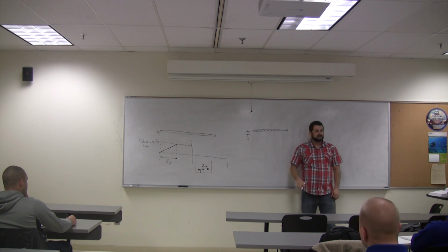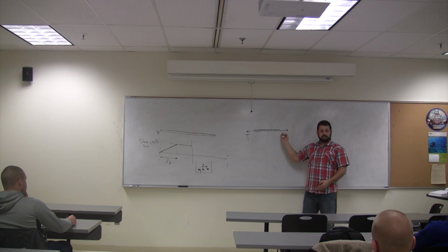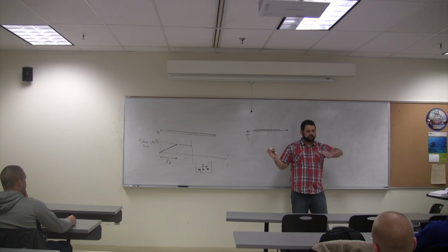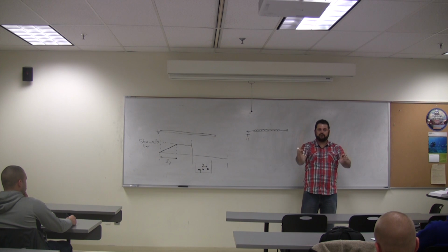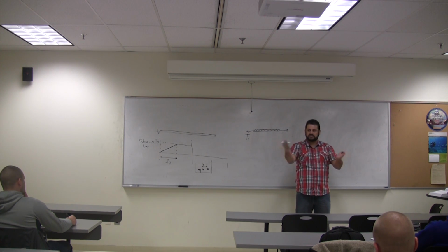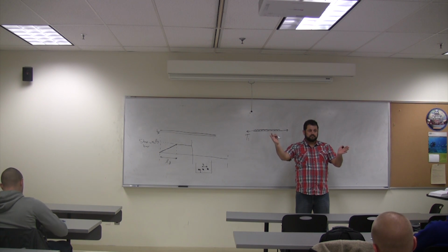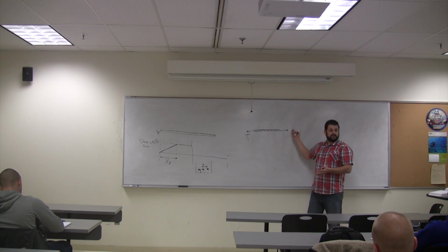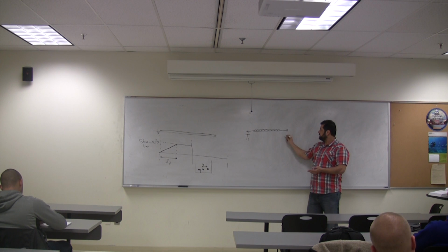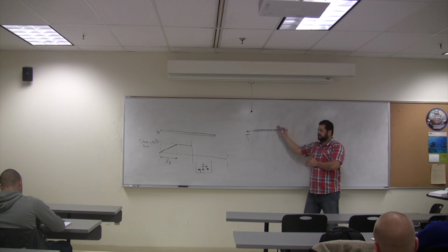It's not. Is the moment here equal to the moment here? In any beam, is the moment to the left equal to the moment to the right at any location? Of course not. The moment is changing, unless you have a constant moment, let's say. So the moment here is different than the moment here. So this T2 usually is greater than T1.